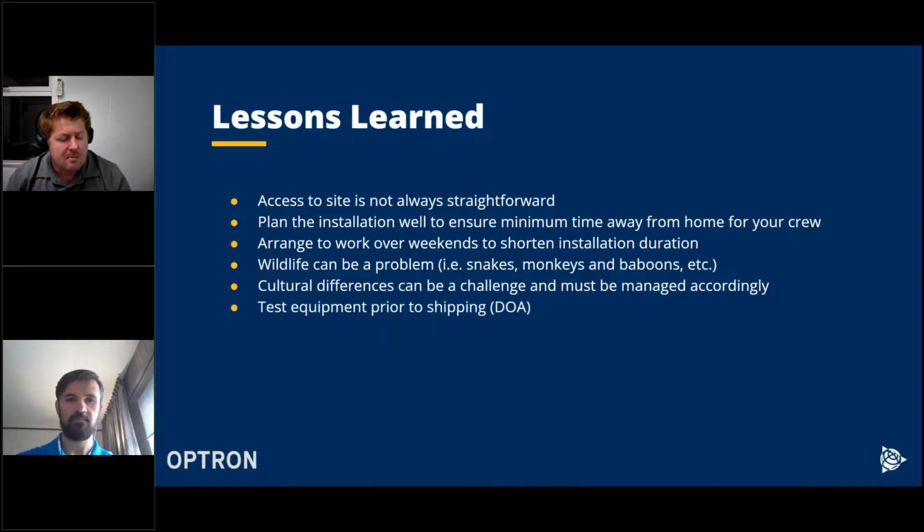And then test your equipment prior to shipping. Sometimes you get devices that get to your office and you install it, you switch it on, and the lights won't even come on. So then at least you're still here in your workshop. You can replace it with a different unit, and you can send a working monitoring station to site, instead of having to get to site and then find out that the devices are dead.